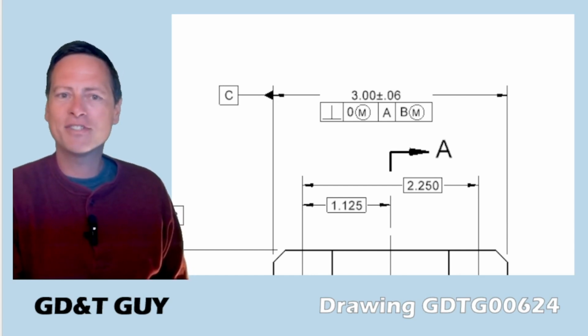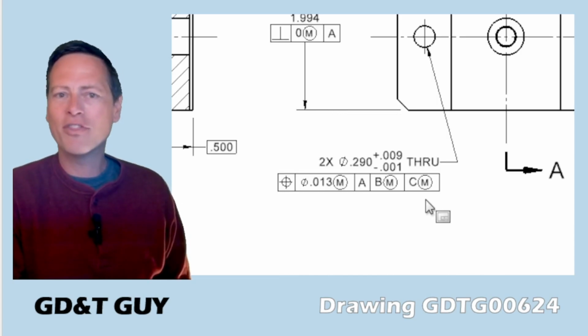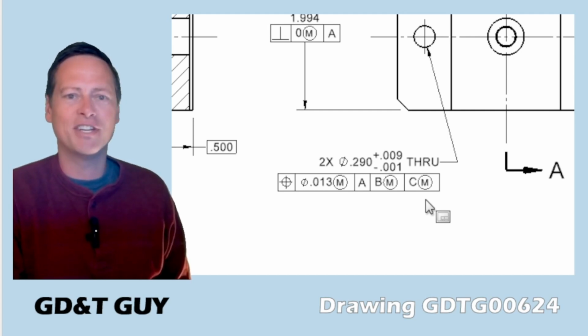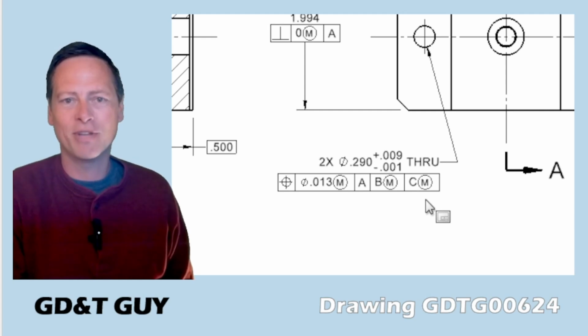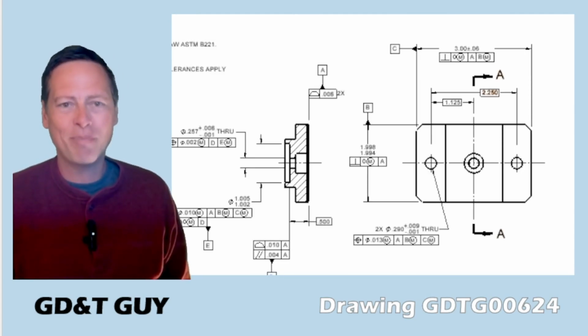Now, I've been saying that this tolerance reflects a design preference I have, that these ends be loose tolerance clearance features. But having it this loose is going to make a big difference when it comes to the material boundary datum modifiers. So we are going to run through a few scenarios for these material boundary modifiers, starting with circle M, like you see here on GD&T 00624.